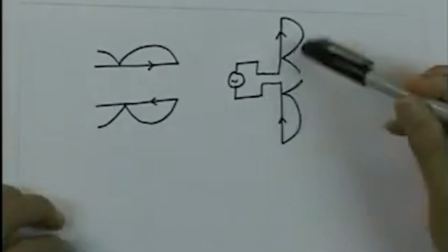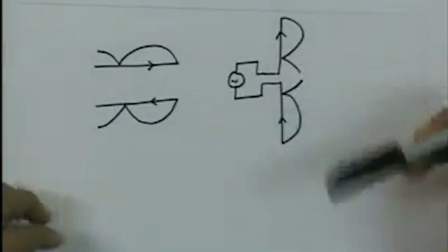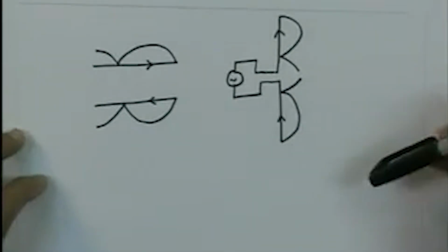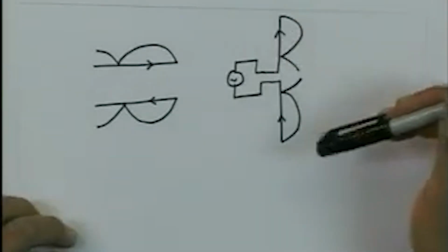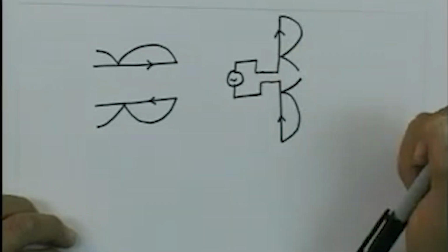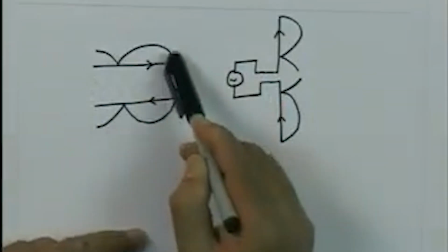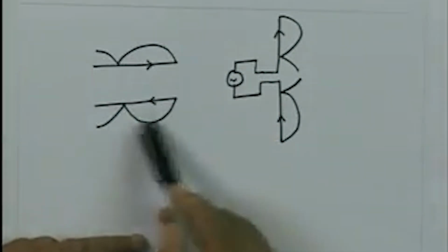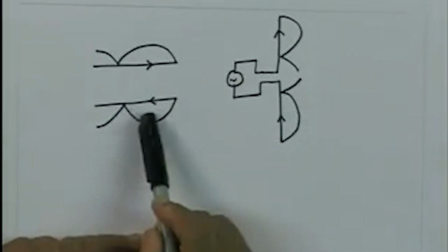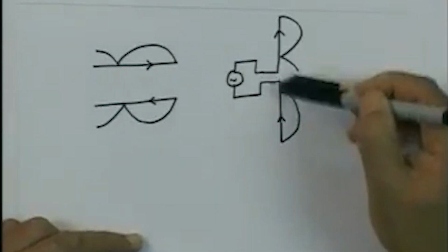Now, the rigorous calculation, using a method like the method of moments or some other methods, also shows that if the dipole is very thin, then the current essentially flows along the length of the dipole, and in an ideal case, when the diameter of the dipole is practically 0, the current distribution on this dipole is almost sinusoidal. We know the distribution, and we can see from the flaring up of the transmission line also that if this is a standing wave, then we have a sinusoidal distribution, which is a standing wave pattern. This pattern remains even when the antenna is completely flared up to become a dipole.